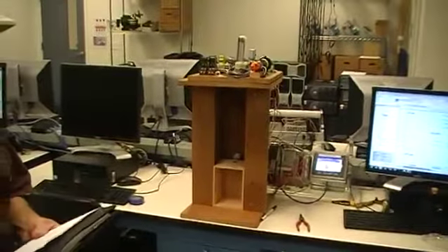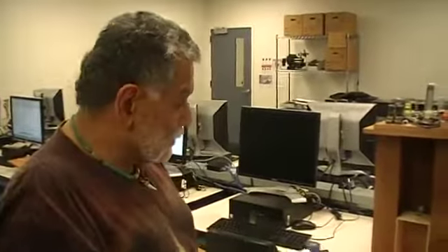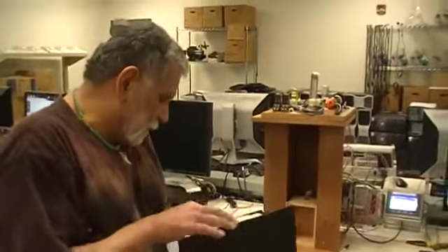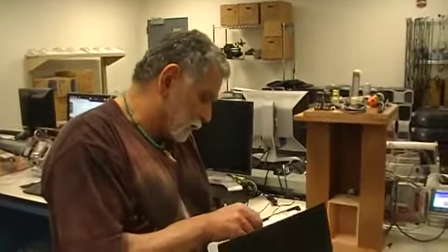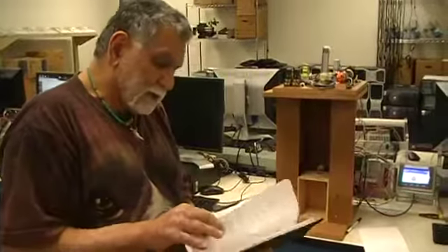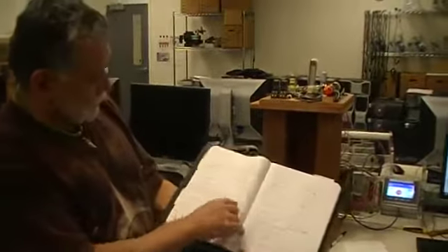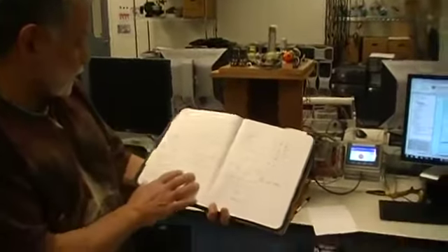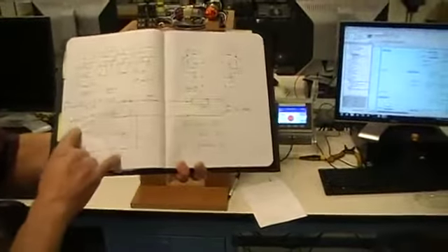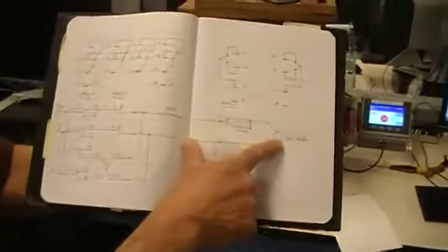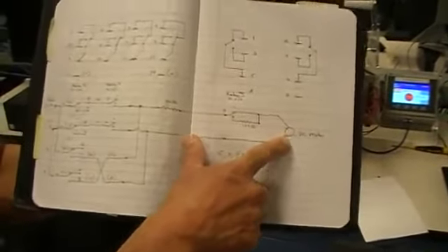Was it hard to wire? No, actually. First of all, I came up with in my head what I wanted it to do, and then I started drawing it out so that it makes sense. When a guy's looking at a print and he's seen a gazillion prints, he knows right away what to look for, which relays are the primary relays, secondary relays, interlocking relays. So I try to draw it as consistently as possible, so you can understand from the beginning of the power all the way down to the output source, which is the DC motor.